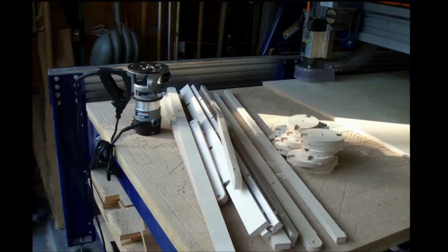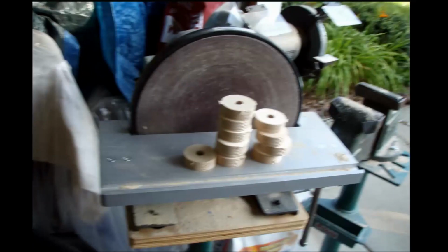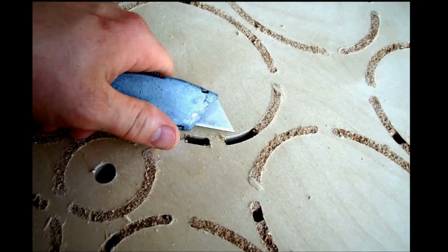A lot of times a tab is easy to be cleaned up with just a 1/4" round over bit on a router. So if you're going to round your parts over anyways, you only need to remove the tab enough to get it so when it slides across the router bit, it'll actually round itself, clean the edge up, give it its round over, and remove the tab. And then a lot of people also will put stuff on disc sanders or spindle sanders, and that is a way to take the tab and clean it off the edge.